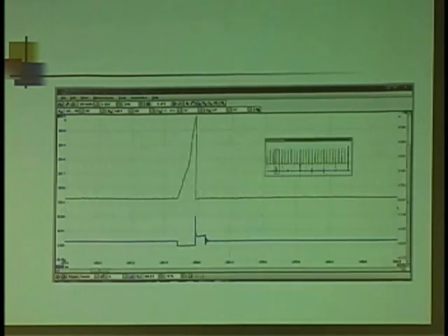If you can't get to the secondary, there's always the primary. You just hook your scope to the ground side. But be careful, if you go to the injector or the primary or any other high voltage output, make sure your scope can handle that. I mean, some of the kickback voltage on a primary coil can be 300 or 400 volts. My scope's only rated at 50. If I put too much into it, it's going to go up in smoke.